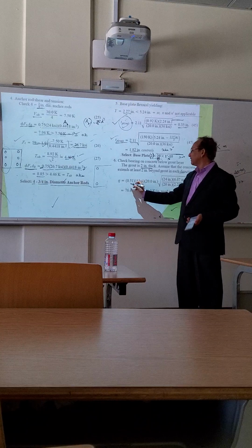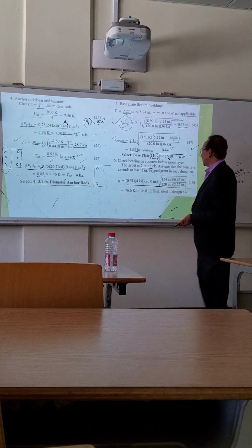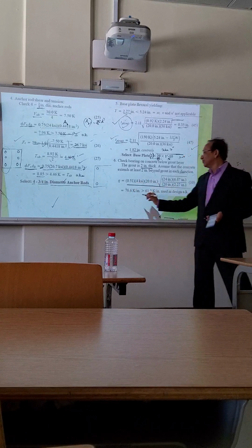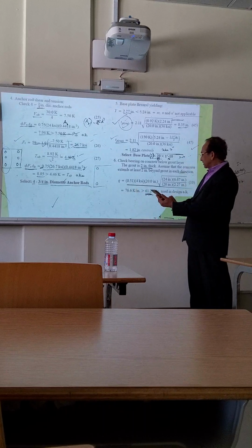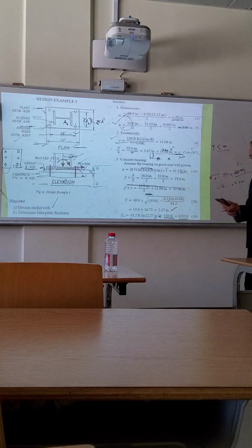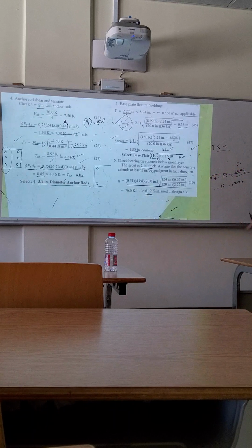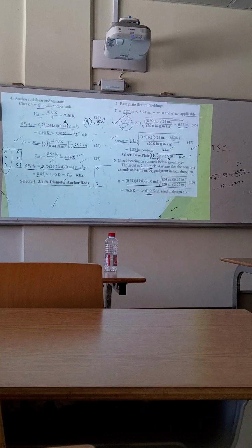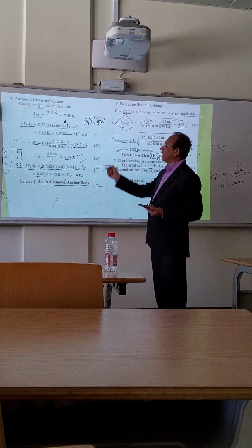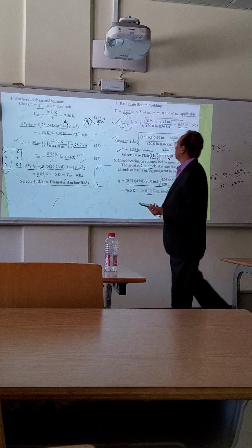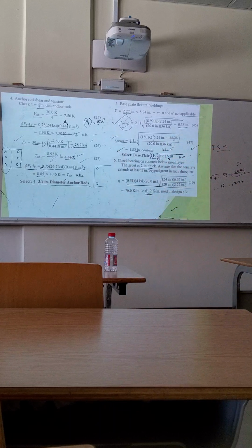So we can calculate this value according to that formula, and we find that this value comes out to be 76.6, which is greater than the capacity we calculated, here 61.2. Only 61.2 is coming from concrete. So with that, now we check for bearing also, thickness of plate and the diameter of the bolt. So this completes your one question.